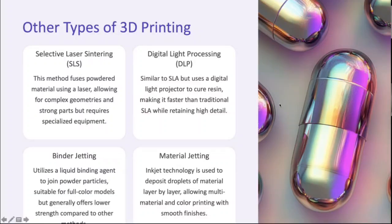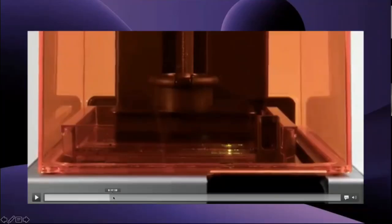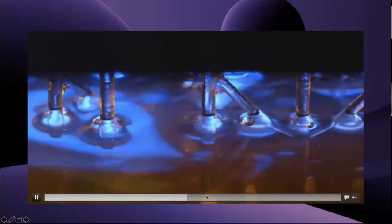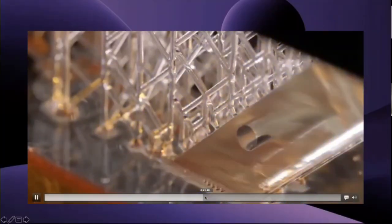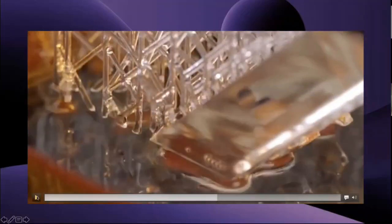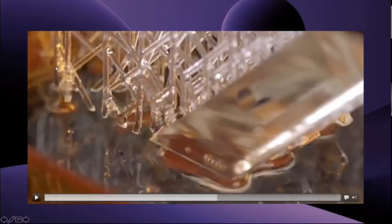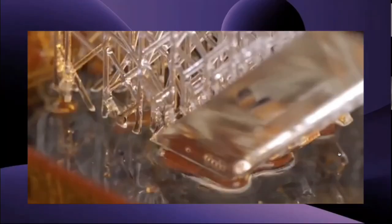I think you saw here, once I go back, I'll play the video here. Automatically from a cartridge. Platform, only a thin layer of liquid in between the platform and the bottom of the tank. Laser at the bottom of the resin tank, drawing a cross-section of the 3D model and selectively hardening the material. The print is built in consecutive layers, each less than 100 microns thick. When a layer is complete, see, if you see here, the part we want to print was from here to here, right? But the liquid was all through this container. So here we need to maintain a certain volume of liquid, but later we can use that liquid for other parts. But we need to maintain a minimum quantity of the liquid to print the parts in the SLA.